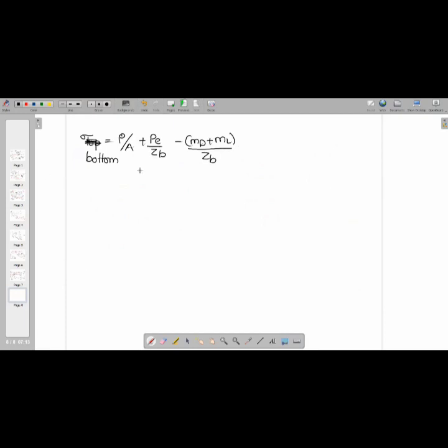Now see, if they tell you first case, concentric tendon, concentric tendon means E will be zero. And also if they don't consider dead load and live load, then in this case E will be zero and dead load is not considered. Stress will be equal to load by area.